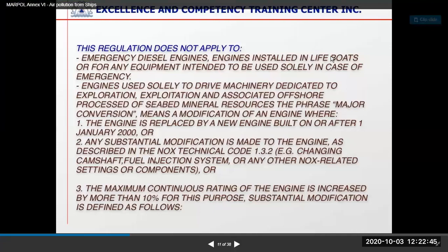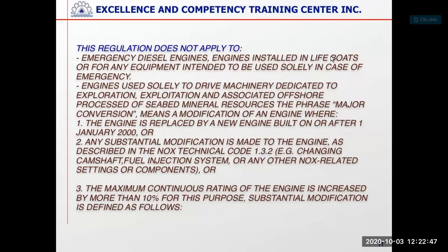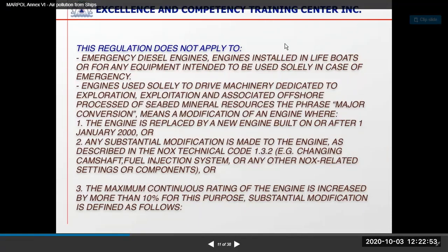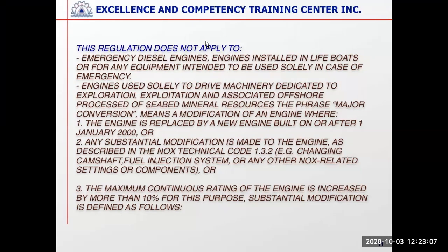It does not apply to engines used for emergency, like a lifeboat engine or your emergency generator, and also those solely used for exploration, like seismic surveys, or exploitation of seabed mineral resources on offshore platforms. In these places, this NOx technical code is not applicable.